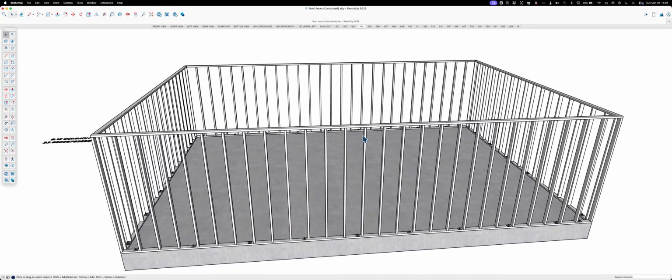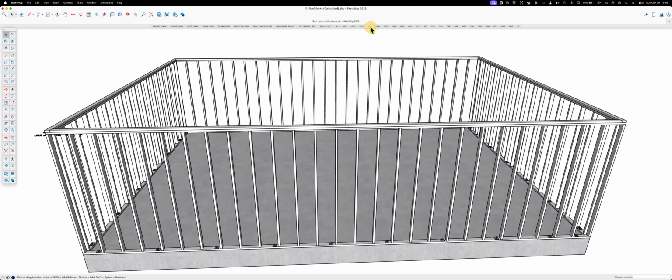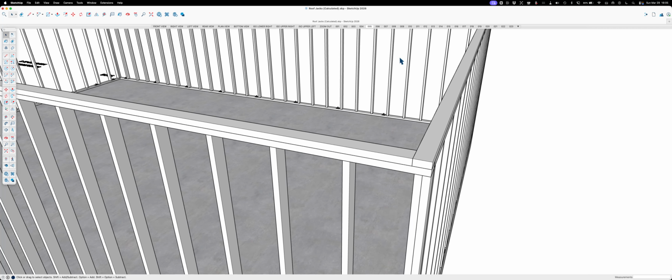So these studs are 104 and 5/8. Once you add a top and double plate, you get a 9 foot 1 1/8 wall. Boom. So if anybody's out there drawing a house and they just draw it to 9 feet, or they call out 9 feet, understand that using pre-cut lumber, you're going to get 9 foot 1 1/8, unless your part of the country doesn't pre-cut the same way as most everyone else.